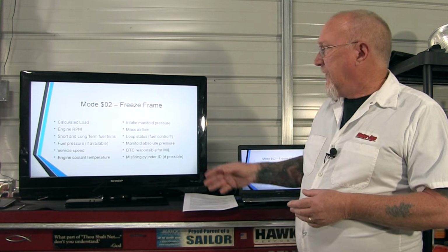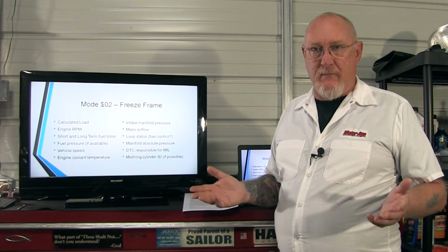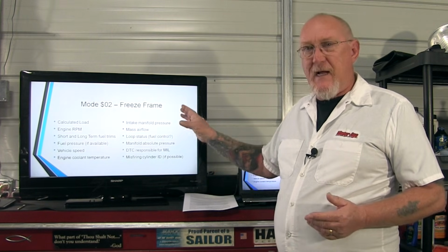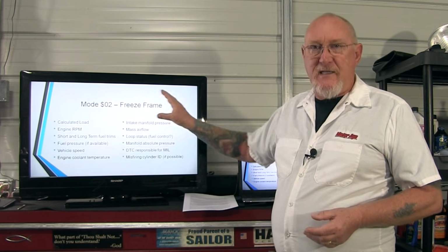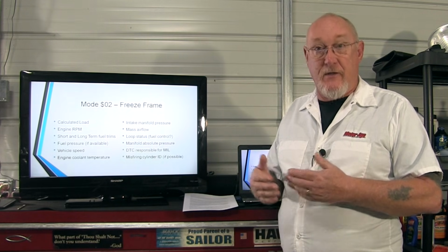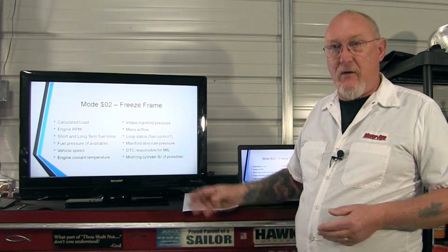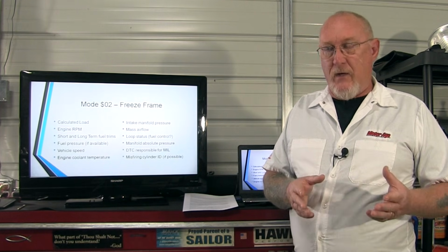If you look at freeze frame data for the non-continuous monitors, say for an evap system monitor, it's really not that much of a help, at least that's my opinion, because it's only going to show me the test conditions that needed to happen in order for that particular section of the monitor to complete itself. So I'm not too concerned about looking at freeze frame when I'm dealing with a non-continuous monitor code.